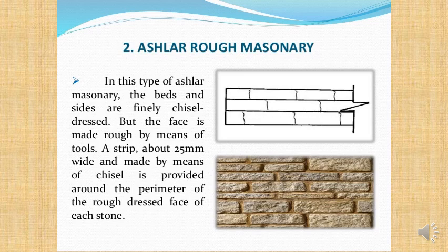Because effectively the hardest part of masonry work in the labour is actually having a nice flat course to work with. You're going to have larger gaps next to each block, but that's not actually as hard and difficult as actually building a nice flat course. And so it's got some of the advantages of rubble masonry and some of the advantages of fine ashlar masonry.